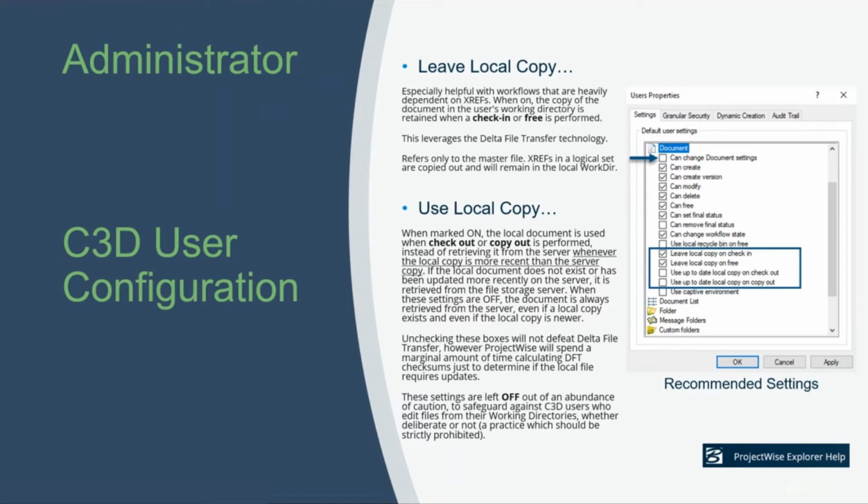From a troubleshooting perspective, when we get involved trying to figure out why something isn't working as desired in Civil 3D, one of the first things we're going to look at is how these 2 settings are affecting what could be going on. And if those are not turned off, chances are that Data Shortcut project is going to be polluted, and a lot of times the only way to really sort it out is to rebuild the whole thing, and nobody wants to go through that.